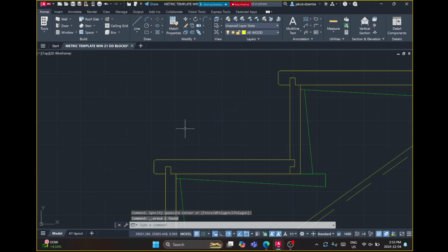We're playing with fire. The reason I don't want to do that is because odds are this is a curve. It's got a lot of little parts you can click on: the beginning of the curve, the middle of the curve, the end of the curve. It's going to be snapping to all kinds of different things. There's a high chance that if I snap to something here, I'm going to snap to something slightly different here. And if I'm even a little bit off from this point, when I extend it, now my stringer is going to be not exactly parallel to this one. It's going to be diagonal compared to it. So it's going to look okay if I look at it on any one stair, but if I expand it to the entire stair section, it's going to start to look stupid.